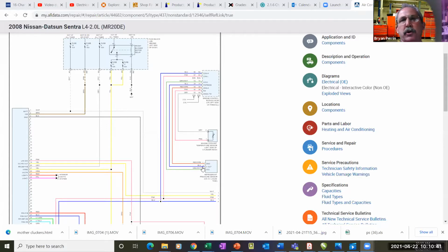So for that matter, you could what? Fool it. Couldn't we run through a resistor or run some other voltage back on the signal out, so that you throw a resistor in there, and now you get 4 volts out, 5 volts out? Now what does it think? Certainly at 2.5 volts, it should turn the compressor on. At too high a voltage, it might not.